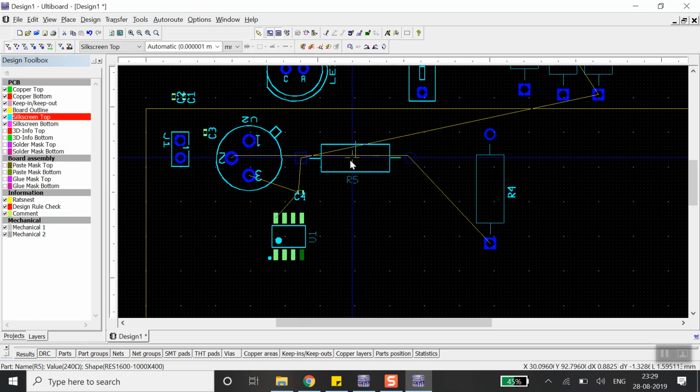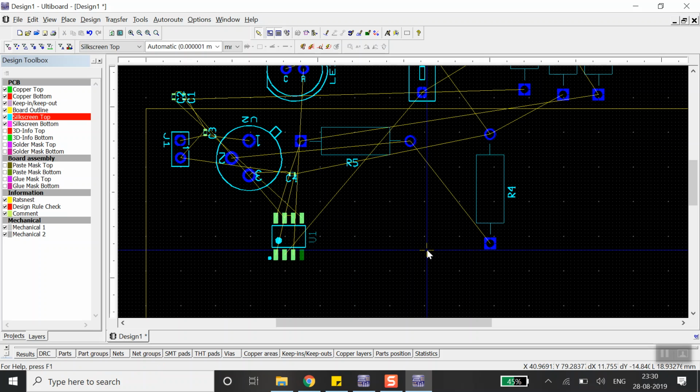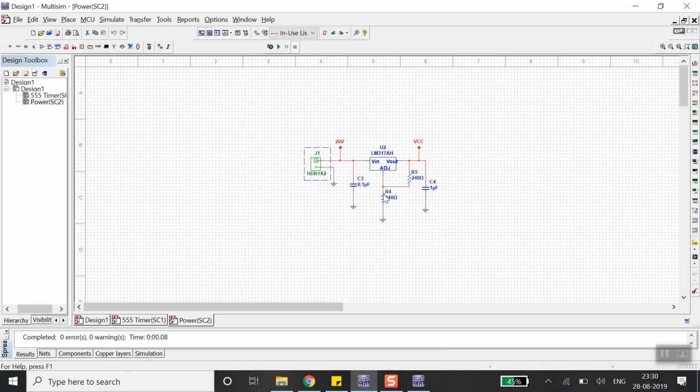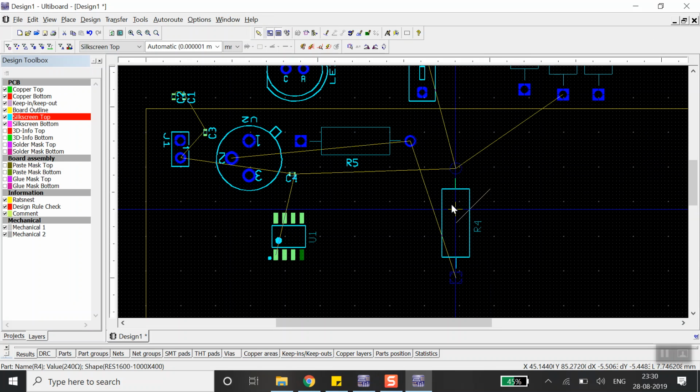That's completely fine. And now you can see, if I rotate the C4 as well, Control R, I believe you will see that the 3rd pin of the LM317 is very near to C4, which got very near to R5 as well. So I'm going to place the R5 over here, and R5 is connected to R4, and I guess R4's next connection on this pin is ground, and which is also going to the adjust. So no problem.